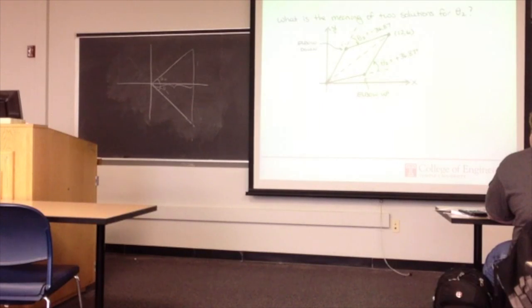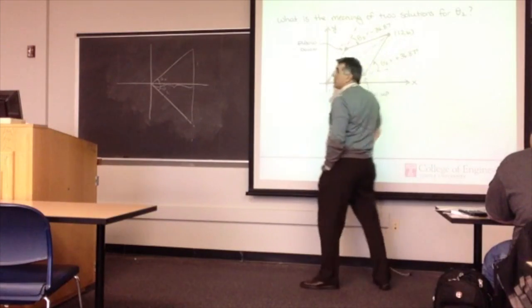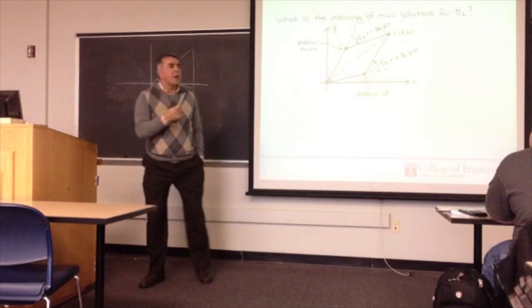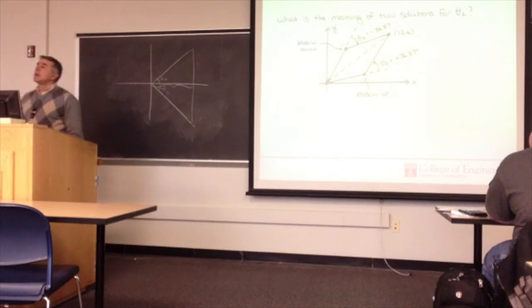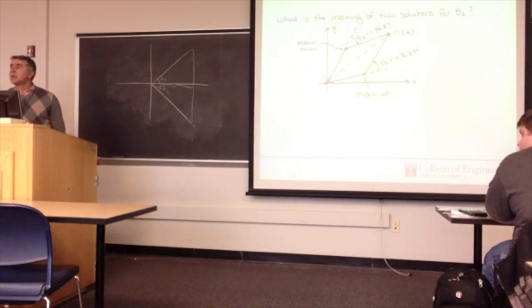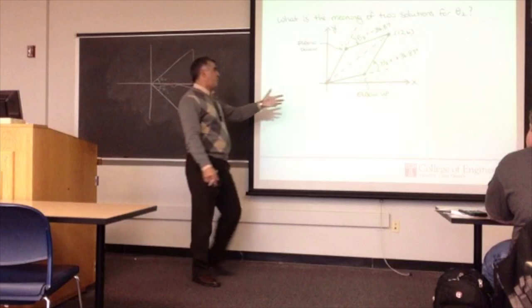So if I have two answers for theta 2, how many answers would you expect to have for theta 1? 2, right. So each of them are complementary with one another. Your objective is really to get to this point. And either one of them is going to get you there. Do you understand? Yes. So basically, when building a robot, you could use it to position the arm in two different ways to reach one point. Absolutely. And then people question, well, if you have two options,